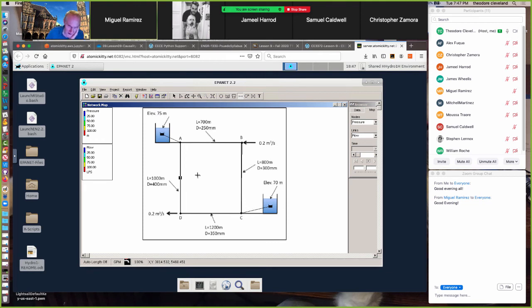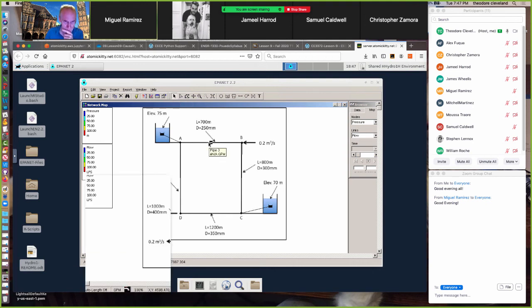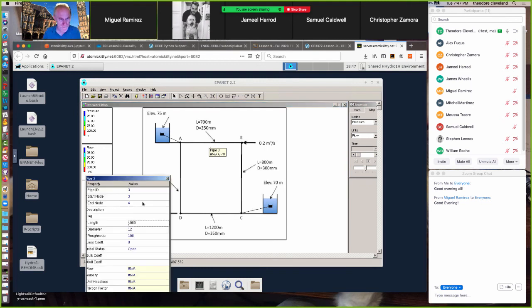And well, now we're ready to go supply parameters to things. So first, let's do pipe AB because we have the information right there in the picture. Its length is 700 meters, 250 millimeter diameter, and let's stick with the cast iron, 0.85 roughness.